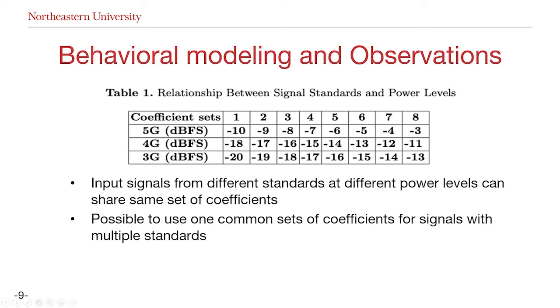And so on and so forth for the other power levels. These results have proved that we can actually build a PA behavior model using a common set of coefficients to deal with signals with multiple standards, or in other words, we will train the model with signals with one standard but apply them to signals with multiple standards.